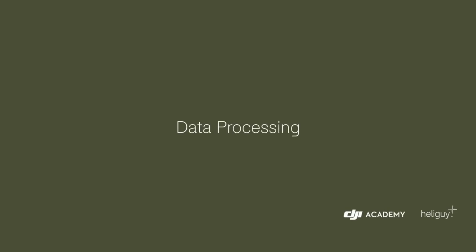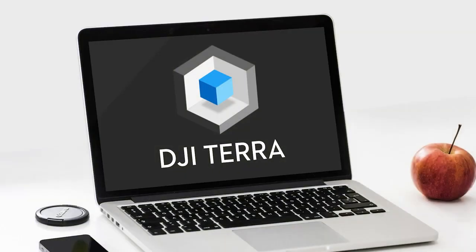Hello and welcome to the section which introduces the first data processing module of the course using DJI Terra software. By the end of this session, you will have generated your 3D point cloud, which is geo-referenced to the WGS84 global coordinate system. It will also provide step-by-step instructions on how to generate a 2D ortho photo using the raw images captured by the L1 sensor.